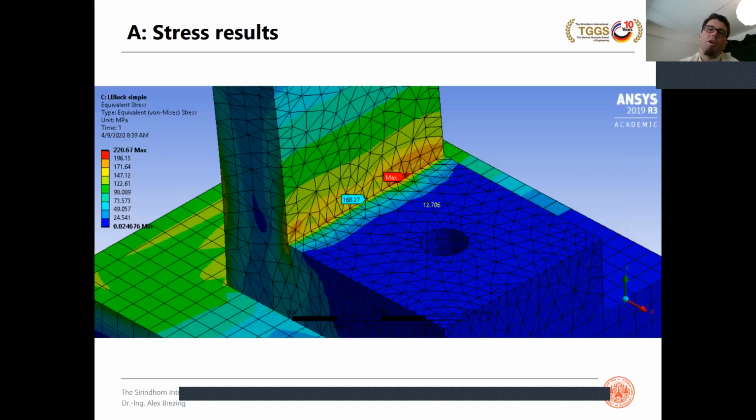Chinnawit gave me a close-up here. What is interesting to note here is that basically all the nodes on this edge have different stress values, and they vary quite a bit. Maximum stress level is 220 megapascal, and a node around the middle of that part just has 170. And this is really resulting from the rather coarse mesh we have.